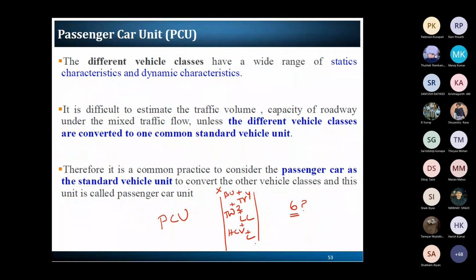From that point of view, it is nothing but a weightage problem. We cannot add X, Y, Z, but we can add X1, X2, X3 and so on. For that, we introduce some weightage. The standard we are assuming is the car as a standard size, and whichever is lower or higher than the car, its dimensions can be given as a weightage.